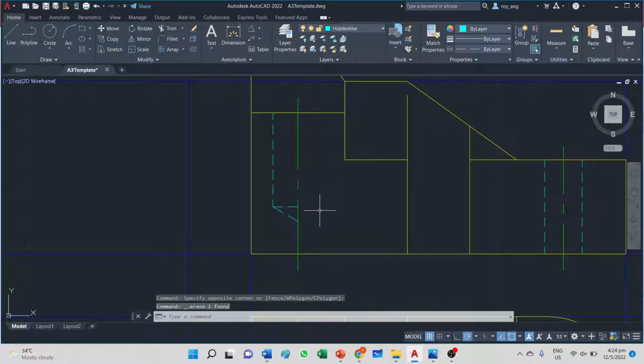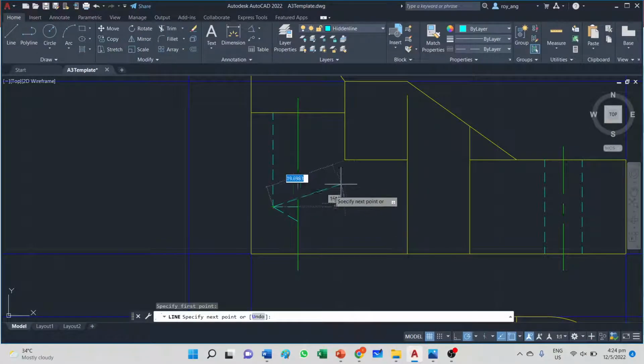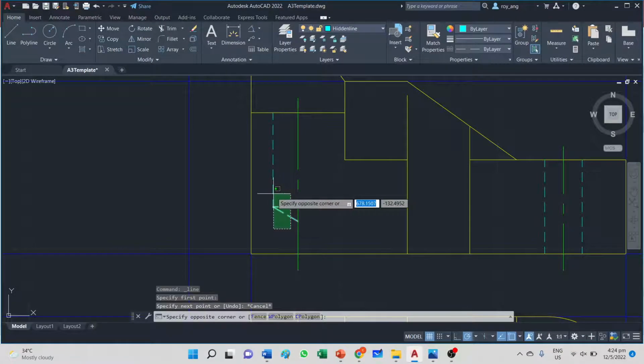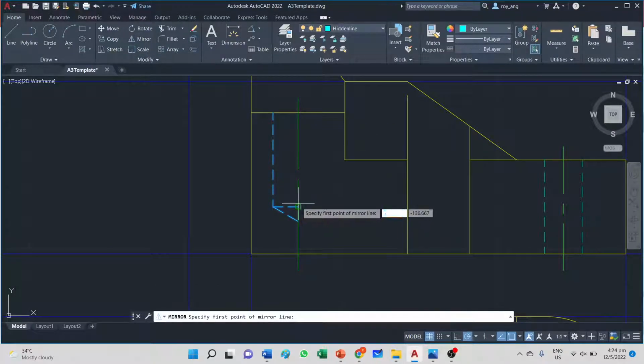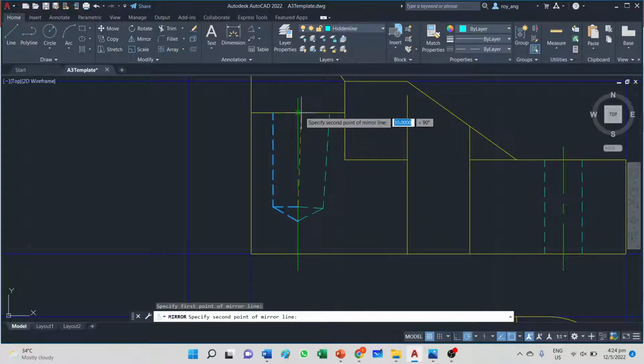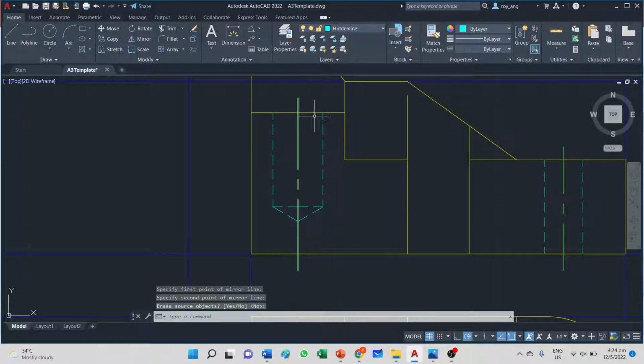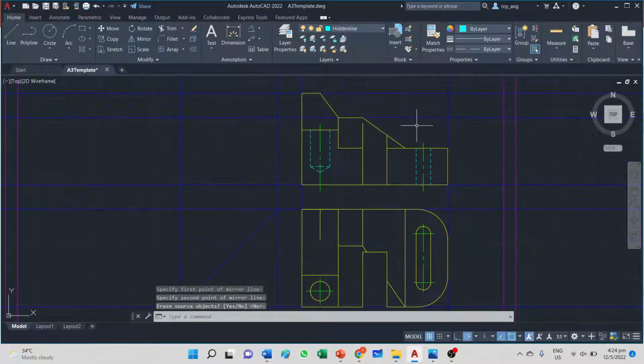Okay. Alternatively, you can memorize, or you can do the math, and actually from this axis to this axis is 30 degrees. So if you don't want to waste time, you just draw a line and make sure it's 30 degrees. Now once this is done, you select the whole thing and you do a mirror command. Then you enter and you have the blind hole. Okay, you have the blind hole, right?